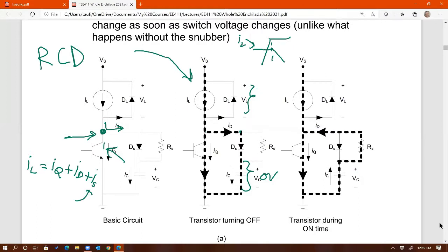Well, this is not a power diode. This is a small diode. It doesn't take much energy, so you could get a diode that has 0.1, 0.2 type of drops, very small. So it doesn't have to handle a crazy amount of power? Nope, it should not. If it does, then there's something wrong with the circuit.